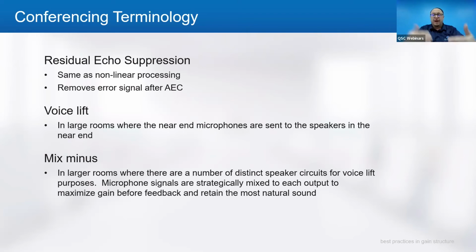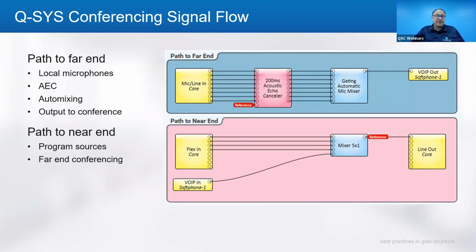And as you get closer to the mics, it will taper, 6 dB, 3 dB, and then anything within 6, 8, 10, 12 feet of the end of the table would be a 0 dB add of that microphone to the loudspeakers there. So that's used sometimes. Once again, this is a little more complex setup type situation.